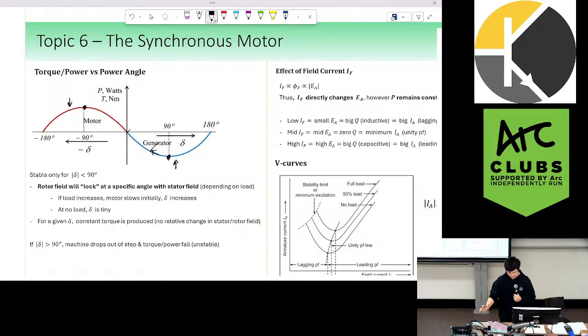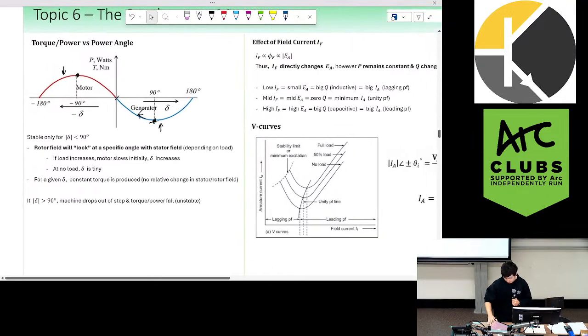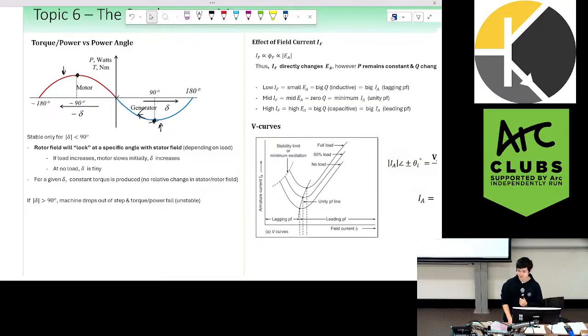But other than that, if your system is requiring more torque, or rather it's consistently dragging it greater than the maximum torque supplyable by the synchronous motor, then, as we mentioned before, we trickle out of synchronicity and return back to zero. If you did this in the lab, you would have heard a little bit of a bang as the machine realizes, wait, it's not synchronous anymore.